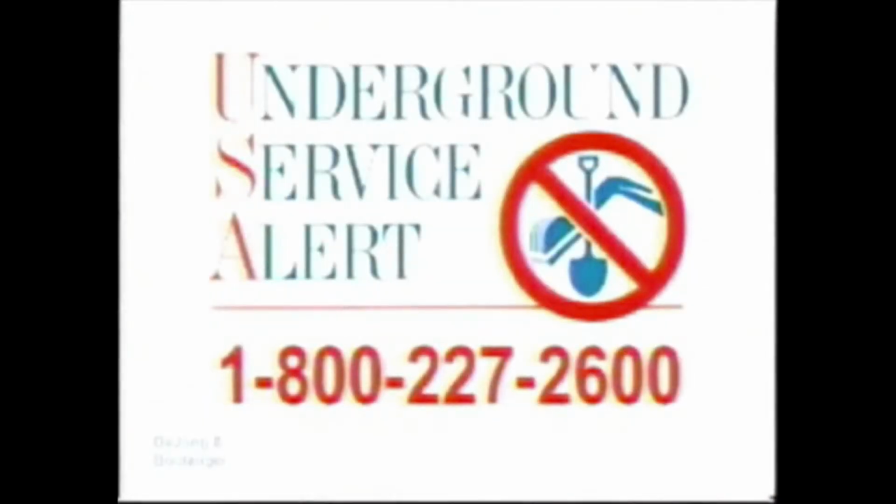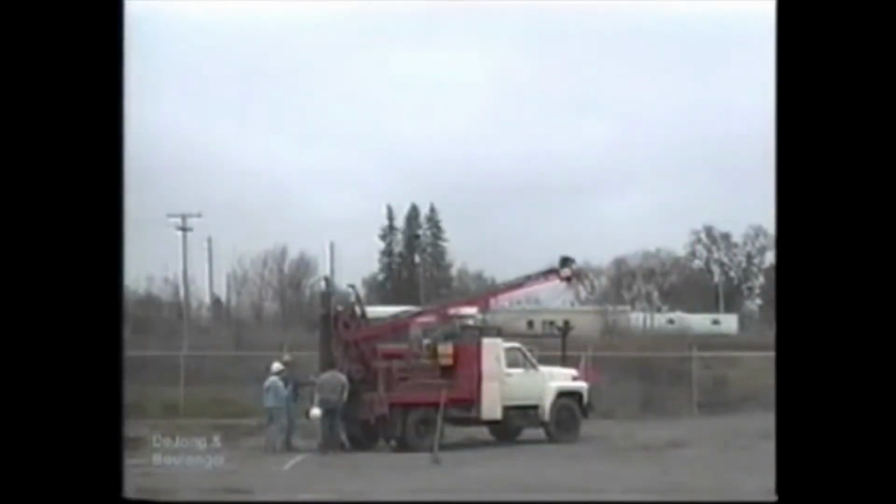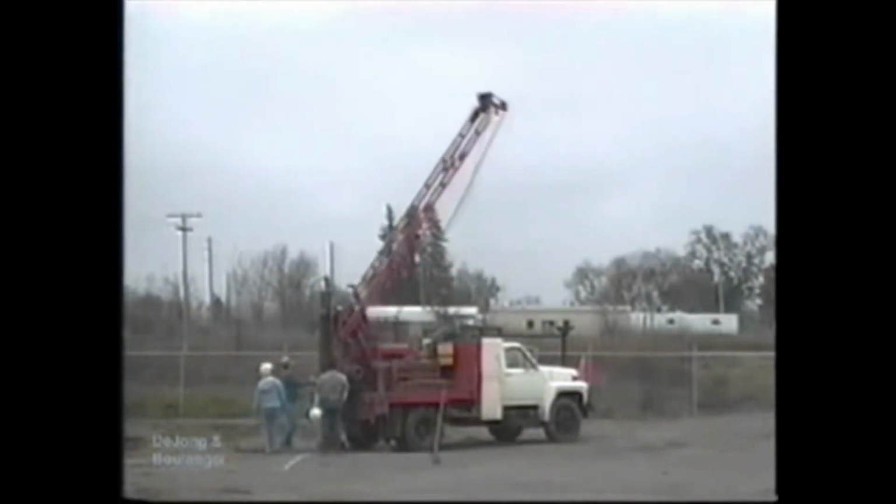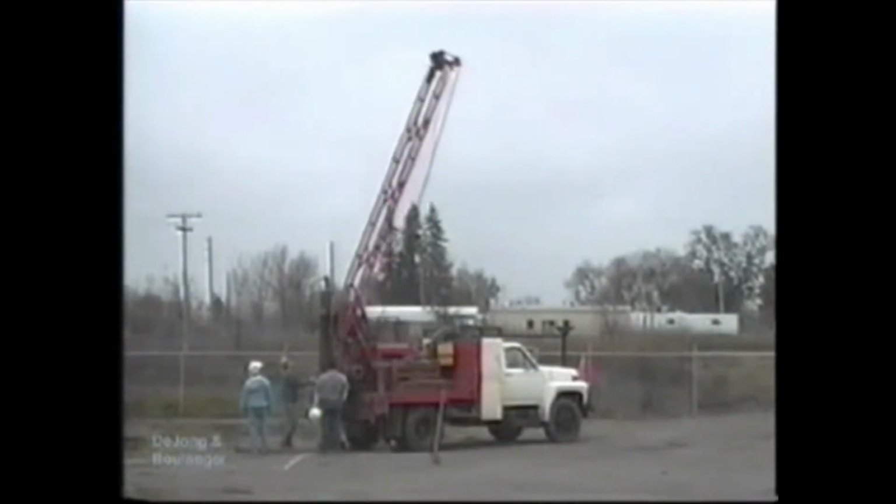In any drilling program, the first step is to check for all possible underground utilities or obstructions, and get an underground service alert clearance as required by law. No drilling should begin without this clearance, no matter where the site is. After the drilling is completed, all boreholes or piezometer installations must be sealed in accordance with state and local regulations. Here a highway drill rig will be used to demonstrate the general features and procedures that are common to all drill rigs. After the drill rig is positioned over a borehole location, the mast is raised and secured and the drill rig is leveled.